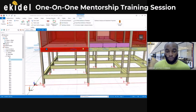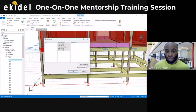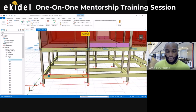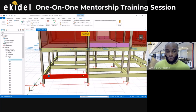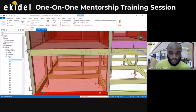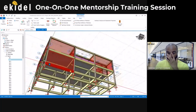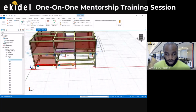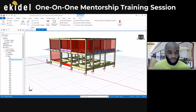So I can just copy this again, because since they are the same height, copy this, then come here, right click here, and then paste that load. Okay, that's fine. So you can see that it is still flushing under the beam. Okay, so I'll do the same thing again now to do a multi-copy, pasting. Click on the first one, scroll down.